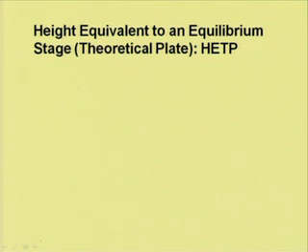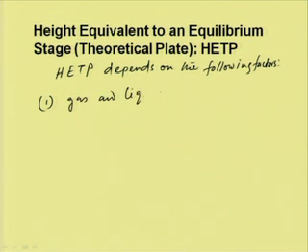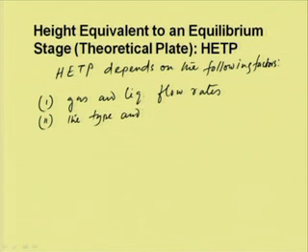This HETP depends on the following factors. One is the gas and liquid flow rates. Second, the type and size of packing.